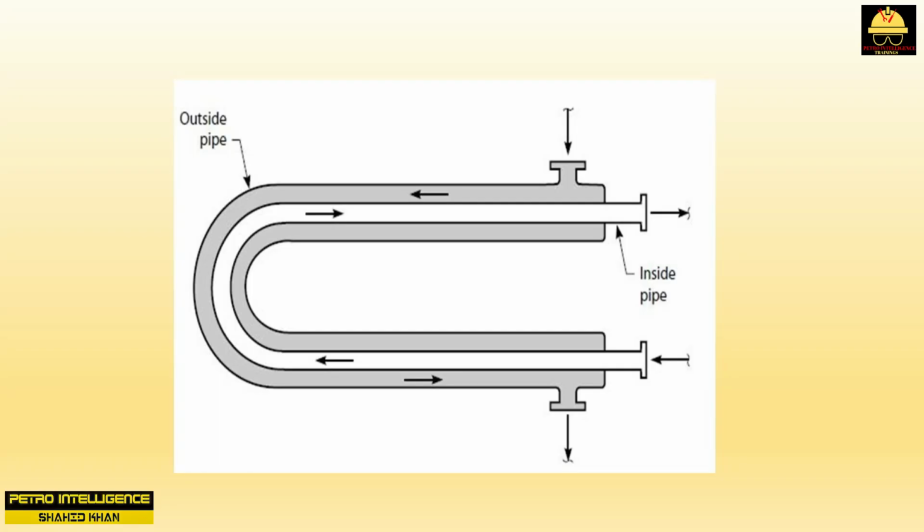Double pipe exchangers. Also called hairpin exchangers, the double pipe heat exchanger, as shown in picture, is the simplest of all types we have discussed. It is nothing more than two concentric pipes. The inner pipe might be 2-inch diameter and the outer pipe 3 inches. Double pipe exchangers are true countercurrent flow heat exchangers. They are rugged and are reasonably cleanable.